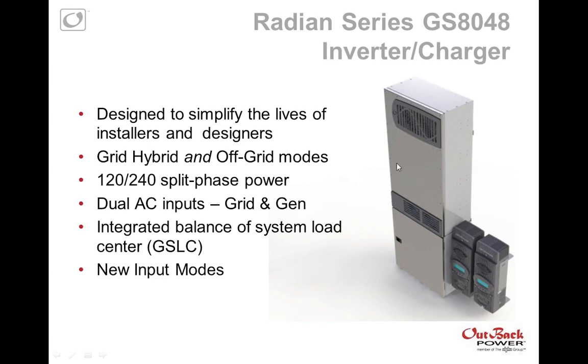One thing that's kind of unique about the architecture is there's just 3 modules inside of there. They run the whole length of the inverter. There's a control board stack and then 2 power modules. And that's it. So you've got 3 modules in there. Power modules come out in less than a minute. The control board stack maybe a minute. So if you ever do need to service it, it's very, very simple to do.